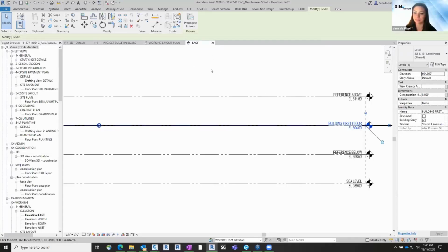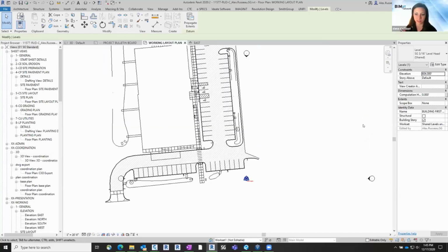So Sarah asks, even though your CAD file you refer to as being dumbed down, you can still bring in the coordinates. So you still acquired the coordinates from it. Yeah, all the actual horizontal line work is going to be set. It's just getting rid of the real life coordinates that are still set within the file. Yeah, all the line work's going to be good. It's stripping the Civil 3D content.